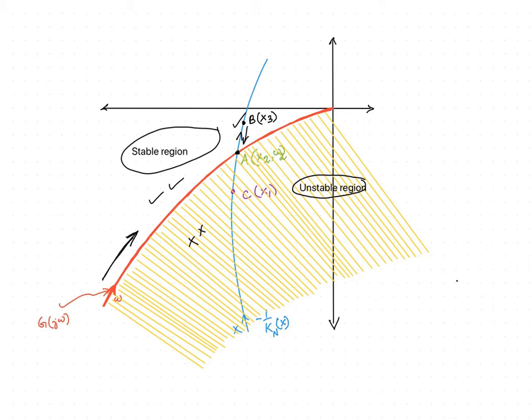Similarly, a perturbation which decreases the amplitude of the input of the nonlinearity shifts the operating point from A to C, which lies in the unstable region. We can see that the input amplitude progressively increases due to the unstable region and the operating point gradually increases its magnitude and it moves back to A. Hence, any disturbance either towards B or C will bring the state back to A. Hence, we can say that capital A represents a stable limit cycle.